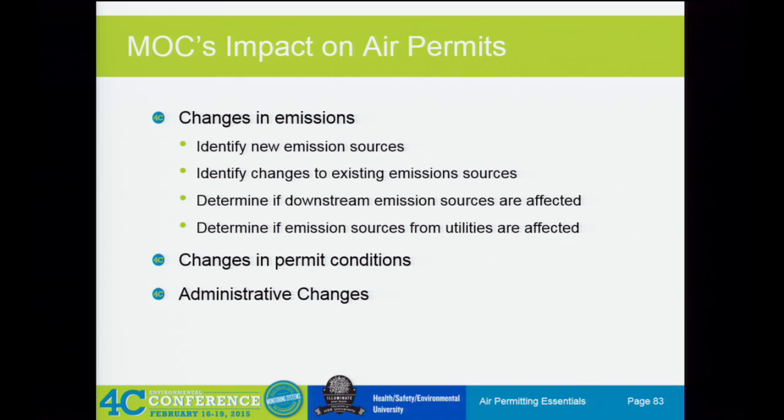So, MOC's impact on air permits. Specifically, there are a lot of things that you want to look at if you are the one reviewing your MOCs. Changes in emissions. You want to identify any new emission sources, identify changes to existing emission sources, determine if there are any downstream emission sources that are affected, and determine if emission sources from utilities are affected.